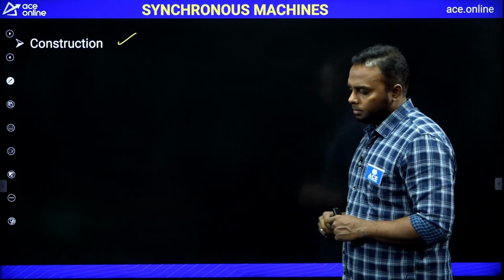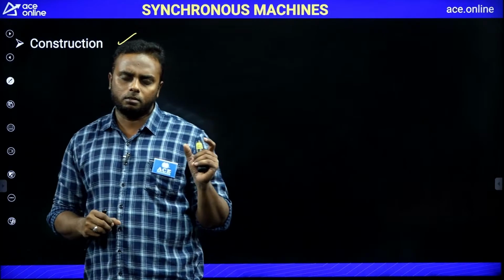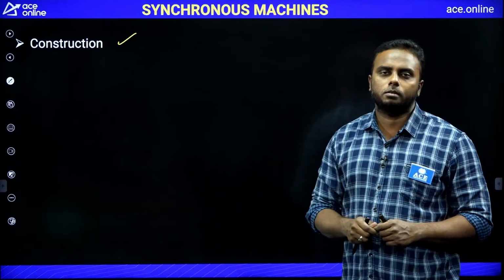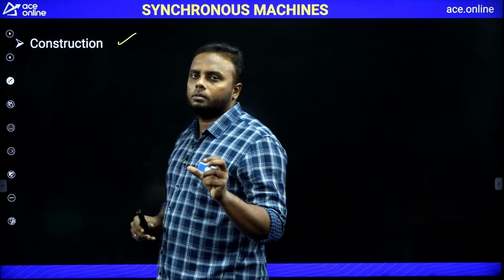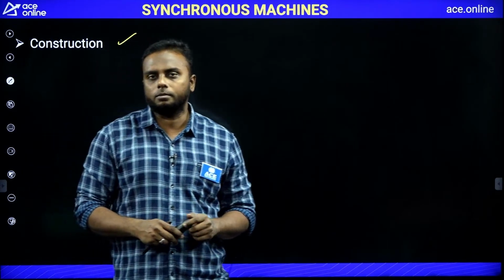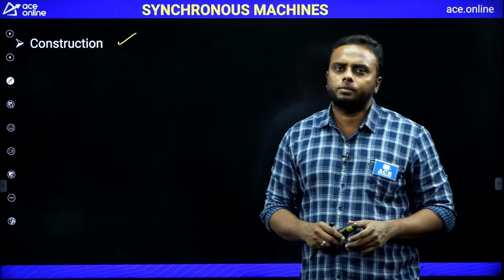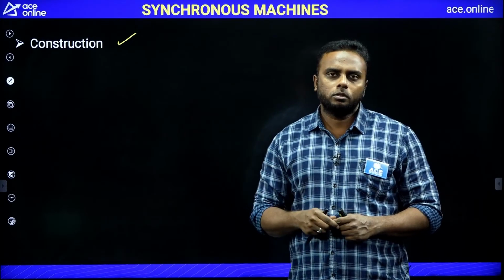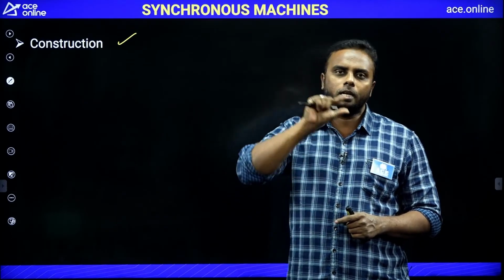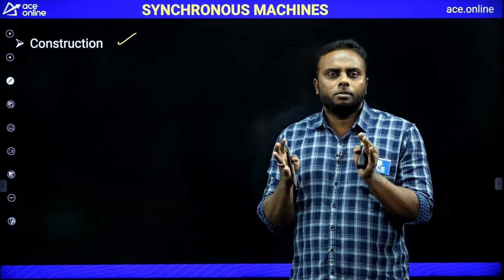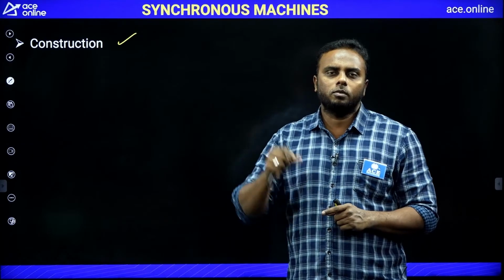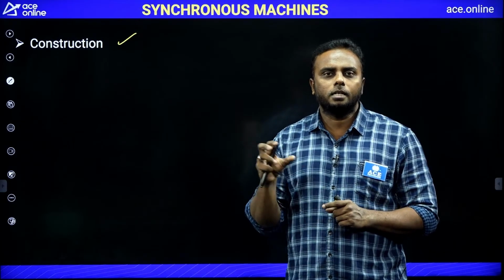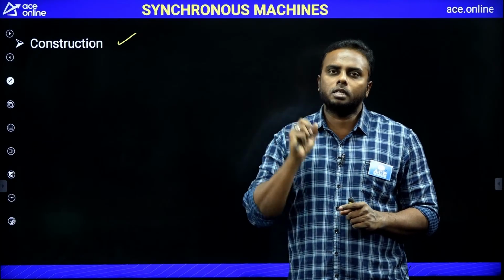Next, in the rotor, there are two types: cylindrical rotor and salient pole rotor. In which type of rotor do we use damper bars to eliminate hunting? These come in the construction details of the rotor. The salient pole rotor has damper bars, used to eliminate hunting, which are placed in the pole faces and short circuited by end rings. These damper bars behave just like a squirrel cage induction motor, however copper bars are inserted there. In the same way here, it functions during transient or hunting conditions. A torque is developed by these damper bars.